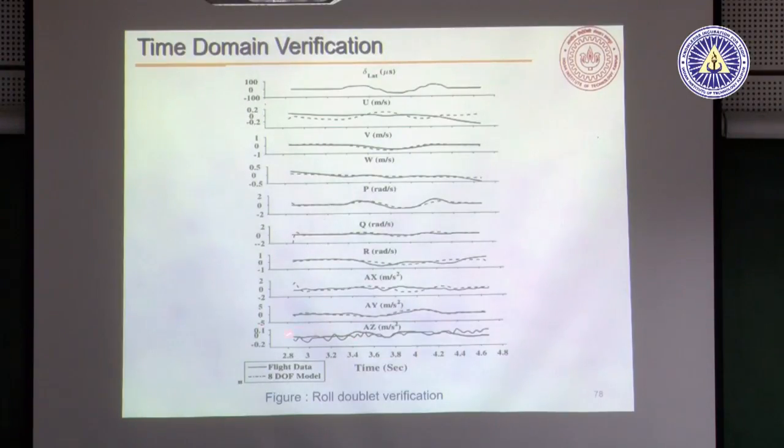It has this oscillation, right? A lot of oscillation is there. Can you tell me what is the source of this oscillation? So this is actually a measure of your rotor thrust in the vertical direction. And this high frequency is basically the oscillation in the force which gets transferred to the fuselage from the rotor. So that is showing up in this somewhat.